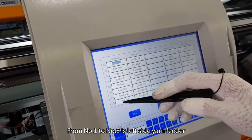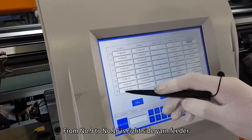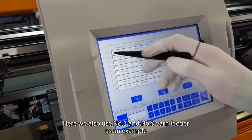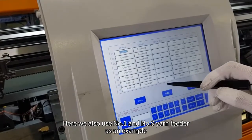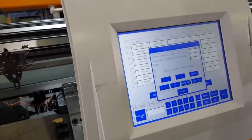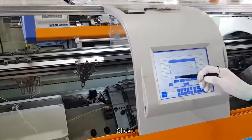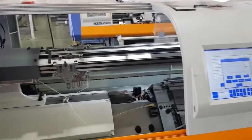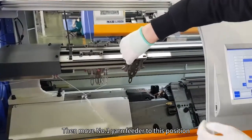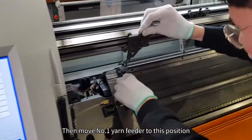From number 1 to number 8 is the left side yarn feeder. From number 9 to number 16 is the right side yarn feeder. Here we also use number 1 and number 9 yarn feeder as an example. Click here, click function. Click 1. Then move number 1 yarn feeder to this position.